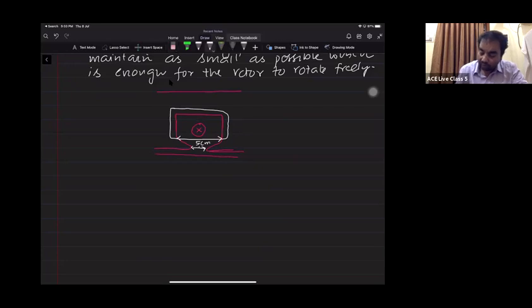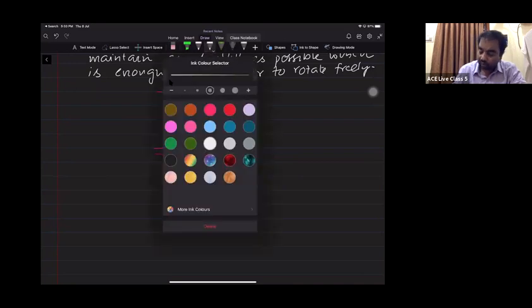If that is the case, the flux will try to take that 5 mm path like this. Then after that 5 mm, the remaining path is 2 mm, crossing the air gap and coming back to that stator again. So that is a 2 mm path.